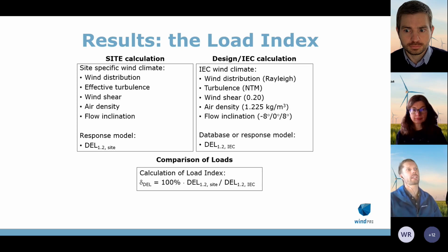We can also apply that to the design climate, and that's what I have here on the right side, and we will get what represents the strength of the wind turbine. And when we take the ratio of these two, we get the load index, which will tell us where the site loads are above or below the design loads.